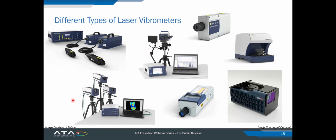And then we've got the classic 3D vector vibration scanning system, or this 3D SLDV system for when you need to capture your out of plane and in plane responses. So if you're looking at describing your shear concentrations in those turbine blades, for an example, you're going to need that 3D system to have not just your out of plane, but your X and Y in plane.